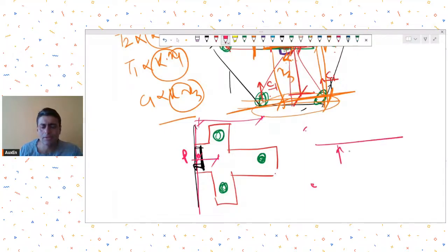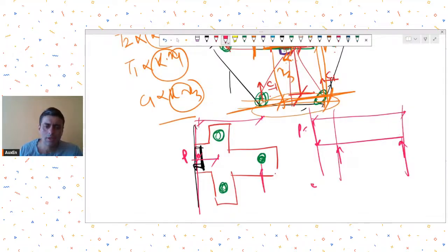Let's say this is my support, this is my support. You have an axial load over here. You know these distances. Now again taking moment about one of the center lines of the piles, you can generate one equation. And over here, let's say if my column axial load is downwards, there will be a tension in this pile, and there will be compression in the other pile.